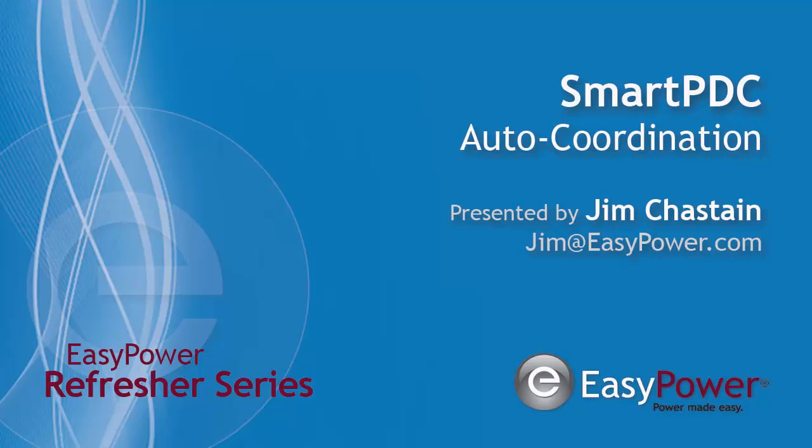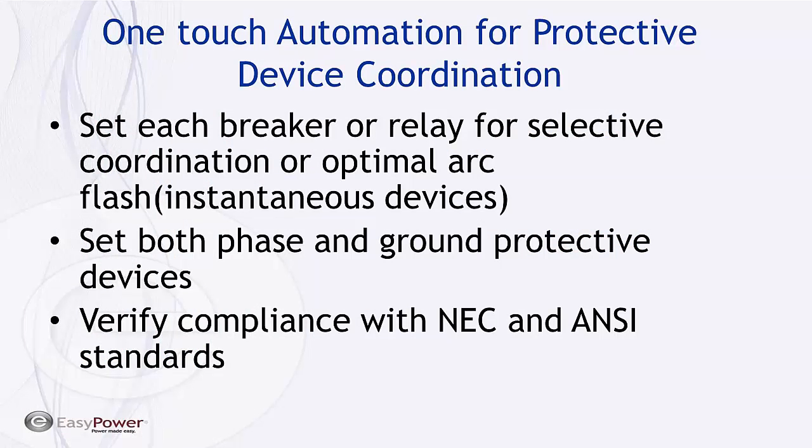Today we're going to talk about SmartPDC and highlight some of the tips on using the tool to make life easier for folks that have to deal with protective device coordination. What the tool does is basically simplify and automate the procedure for doing protective device coordination by setting each breaker or relay for selective coordination or optimal arc flash for instantaneous devices. In reality, it actually kind of ignores the arc flash results when it comes to doing the coordination. It has the ability to set both phase and ground protective devices and verify compliance with ANSI and NEC standards.